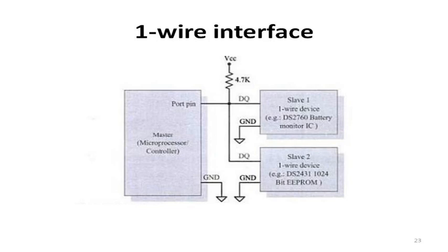The timing logic of master and slave must measure and generate a digital pulse of various width. When it is idle, a high impedance path between one wire bus and the operating voltage puts the one wire bus in the logic high state.